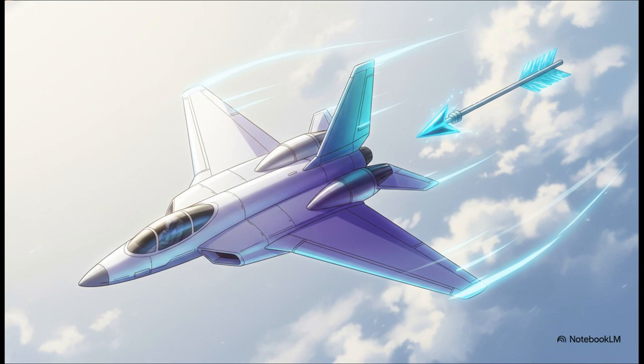Sweepback wings also provide a minor assist here. If the plane yaws to the right, the wing suddenly presents a longer leading edge to the wind, increasing its drag, which smoothly pulls the nose right back to the center.